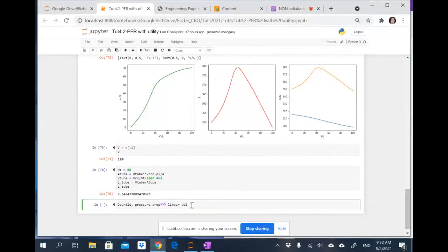And as you will see next, after the linear velocity, it's going to impact on mass transfer. It can impact on the reactors where mass transfer to get your products to or from your catalyst surface. The linear velocity is a very important parameter. So if I increase the number of tubes, I reduce the linear velocity for the same flow rate of reactants that must flow through it. And that can impact on those design parameters. So it's fun.